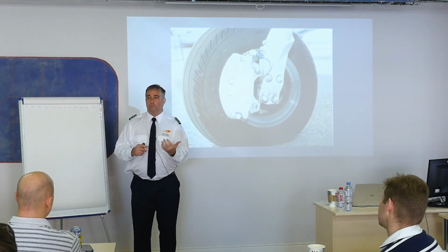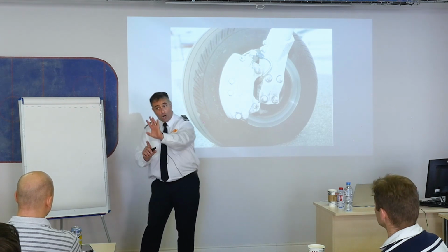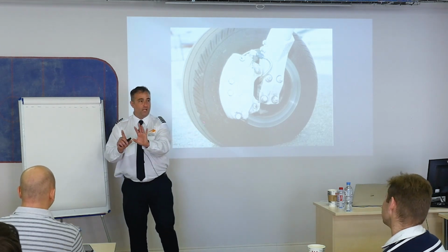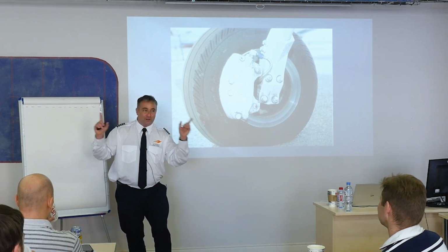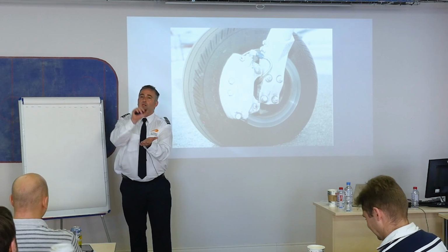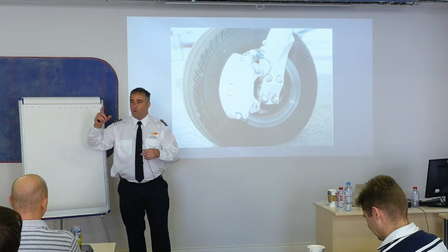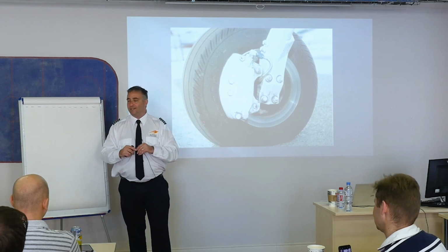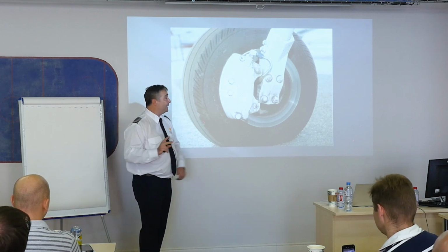Use aerodynamic braking. Make the airplane fly slower as you approach. Don't stall before you touch the ground, right? But make it slower before you approach. There's a little bit of medium ground there, okay? Don't get on the ground and apply these brakes like you're driving a 2020 911 with anti-skid. This thing does not have very good brakes at all, okay?